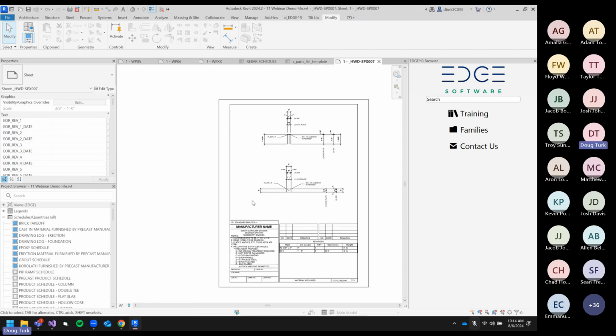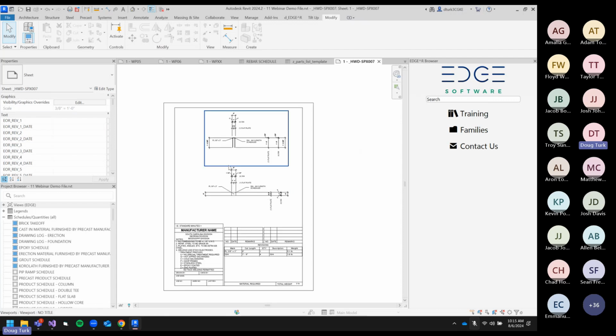So that was a very, very long-winded explanation of the family setups. But to recap, the important things there are to do the HWD bound lines and the HWD dim lines correctly, and to either set a material with a structural density or set a weight per unit for the subcomponents involved in that hardware. As long as you set all of those things up, it should be compatible with the hardware detail tool. I believe that's all I have for that, and that does include the new features and updated functionalities.